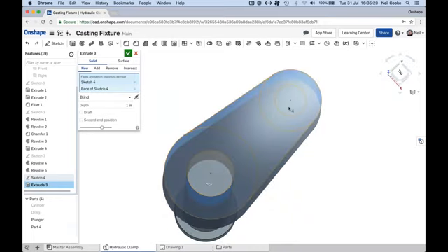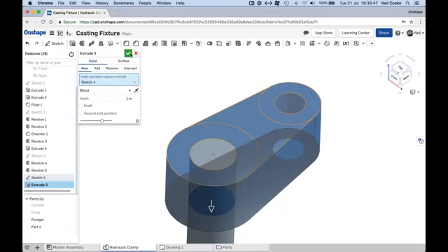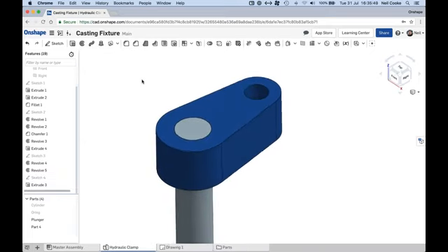So when typically you want to lay out multiple contours, you don't need to bother trimming, just sketch everything that you need to see. So it could be a layout for a mechanism, for example. Just need to sketch what you need to create, and then just choose the areas which make up the individual bodies, and that will generate the shape for you.